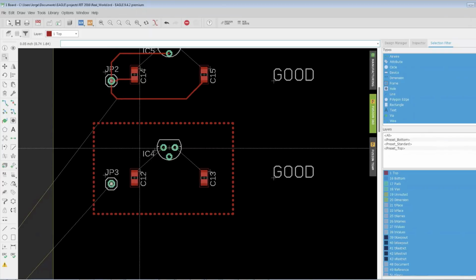Okay? And because it's just a plane of copper, unless the current is going through large distances, these impedances are going to be small. Okay? So that's what's really going on. You can still think of a copper plane as making it easy for all the return paths to go back to their origin. Okay, but don't think of it as just a sink of current, and as long as it's connected to the ground plane, everything is going to be okay, because that may not be the case. If we have a lot of signals going around here, you have to be careful on how you route them, because you may cause return paths to run over each other, to intersect, and that can increase noise.